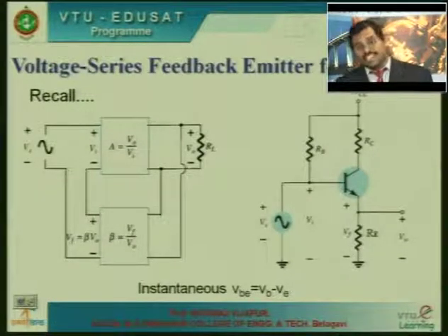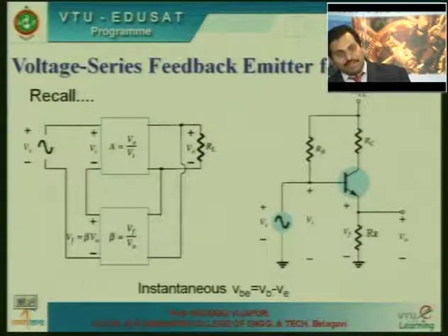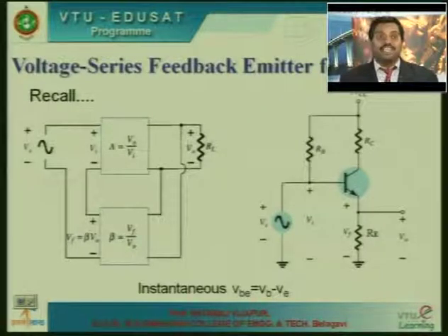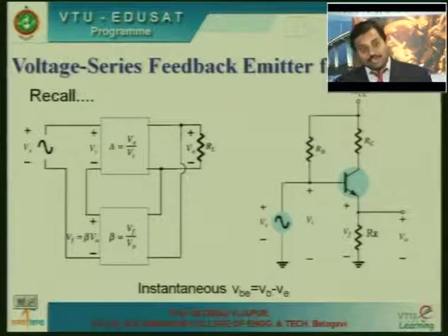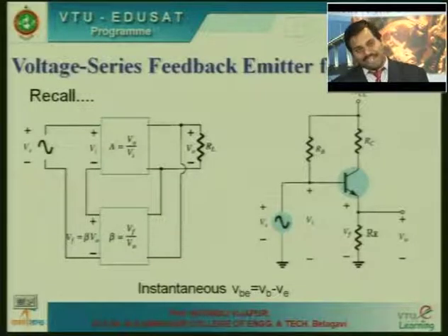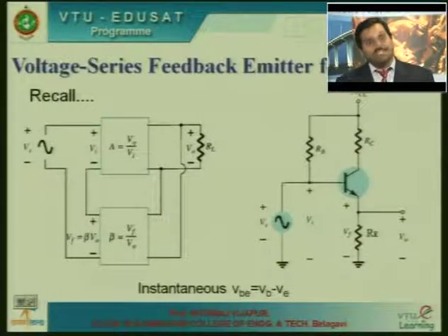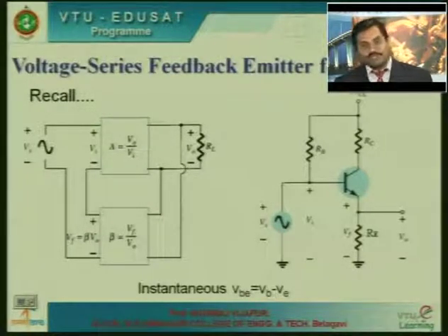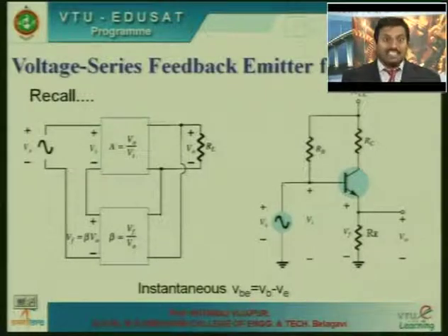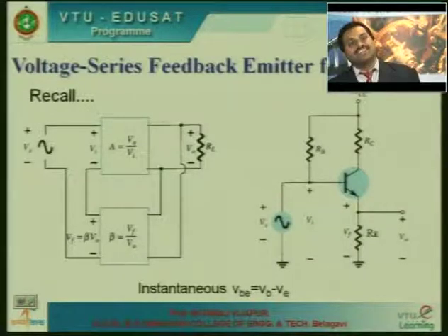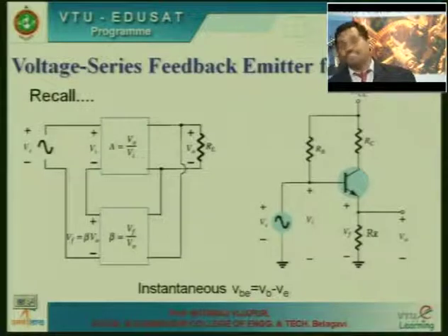We know that a BJT or transistor amplifier can be biased in common base configuration, common emitter configuration and common collector configuration. In common base configuration, base is made common between emitter and collector. Emitter acts as an input and collector acts as an output. In common emitter configuration, emitter is made common, the signal is applied to the base and output is taken from the collector. In both configurations, common emitter and common base, the output is taken from the collector junction. Collector is a reverse biased junction. You will observe a high output voltage, or the voltage gain is high.